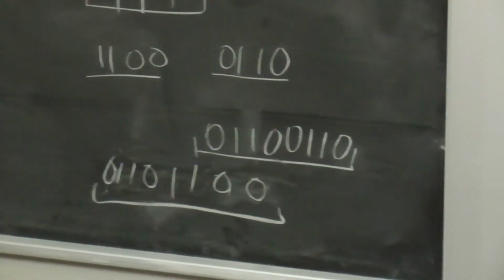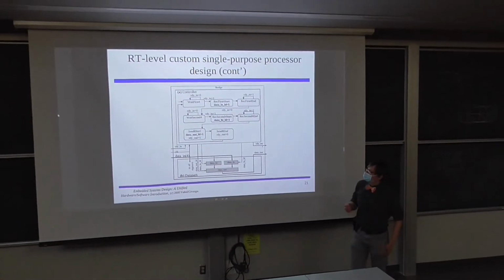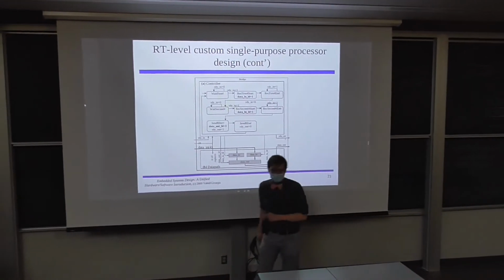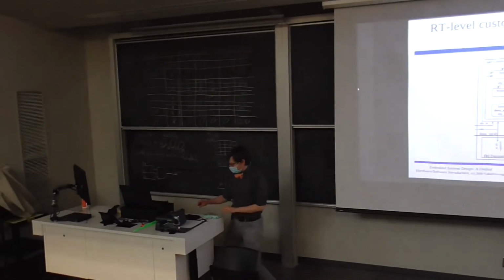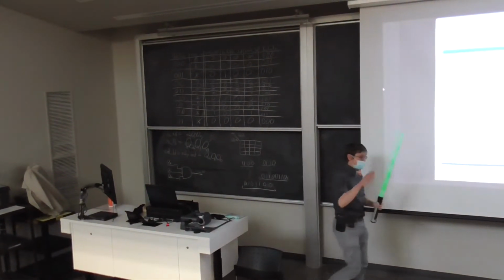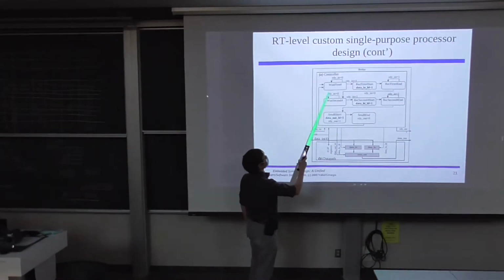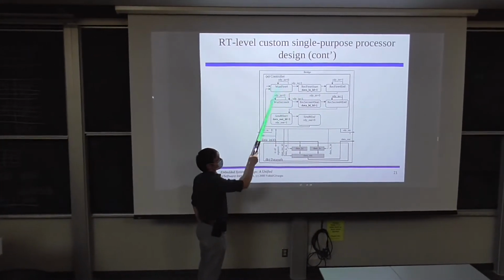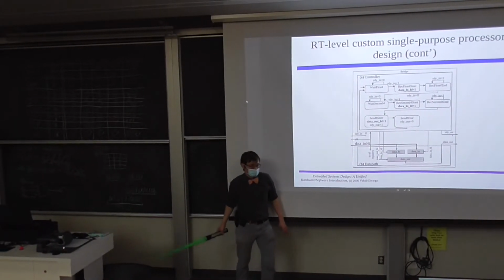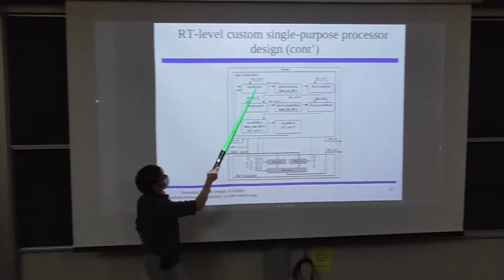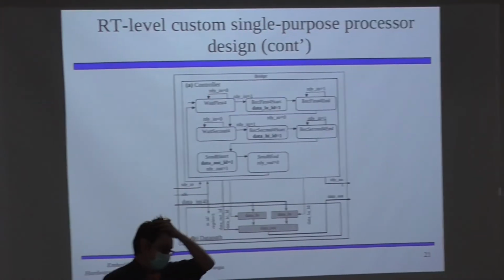Back to you. Yeah. So I'm just a bit lost how we get from the finite state machine we have to the actual values that we put into the table. Good. So this comes from direct observation of the things going on in the specific states themselves. Okay. So essentially, it's easy as long as you know how to read the diagram, right? So it always makes sense to start at the beginning, right? This is the first state. We don't have any statements inside of this state that would indicate that we're loading a register, right? Because there's nothing in it. This is just a label, right? So it's doing nothing except controlling flow to the next state. That's the purpose of this state.